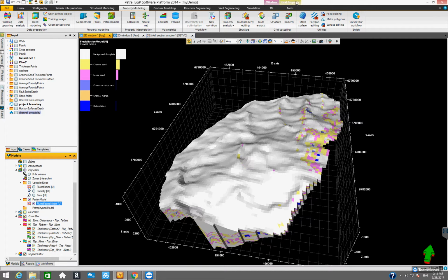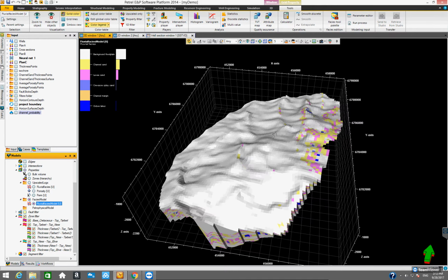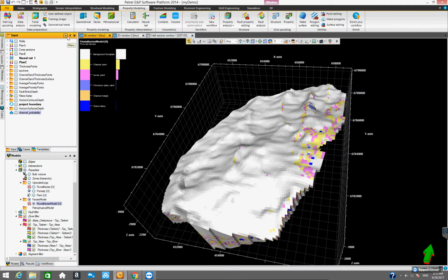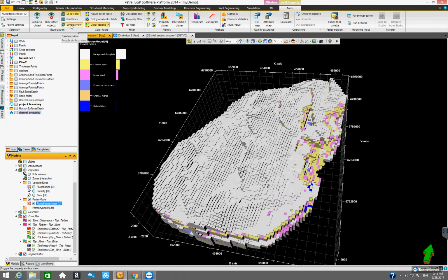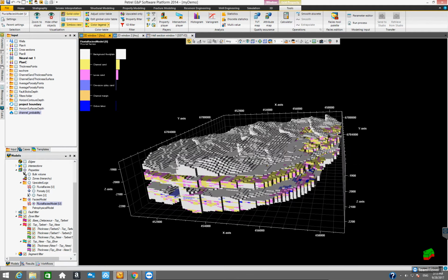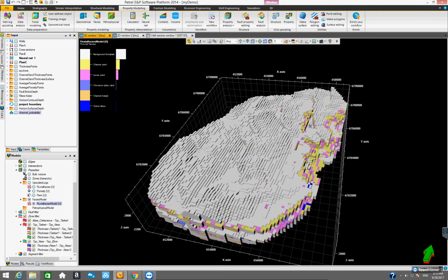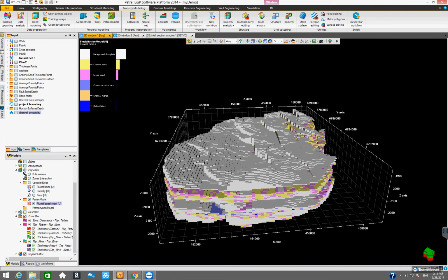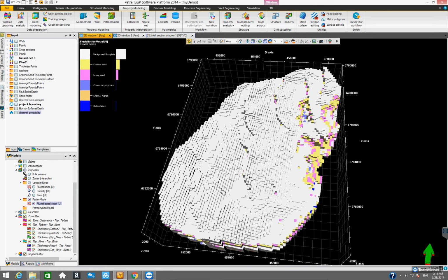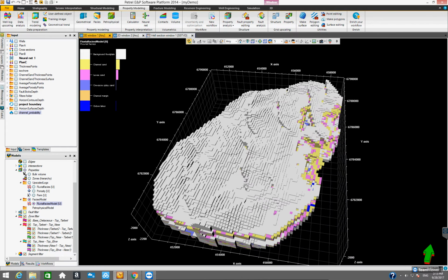If we click on the fluvial facies model and then go to the grid properties, there's also something called a Simbox view. If you click on it, it's going to rearrange the model as if there had been no structural changes since the deposition, right? So if you click on the Simbox view, everything is going to flatten out, as if the entire structure is static, and hasn't gone through any structural changes after deposition.